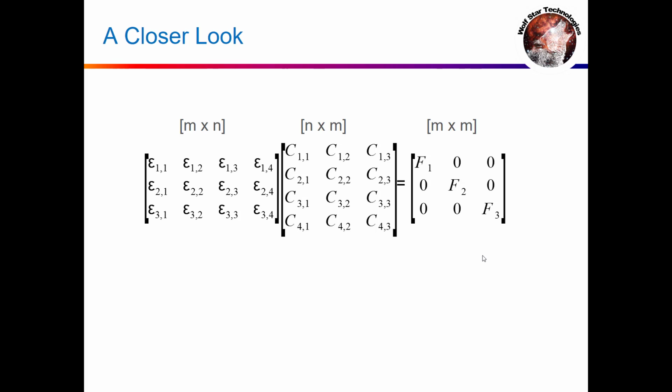So I've talked a lot about loads here, but let me talk about that a little bit more. The loads could be anything. They can be point loads, they can be moments, they can be pressure loads, they could be thermal loads, they could be unit displacements. They could actually even be mode shapes. So we could go in and calculate the mode shapes on a structure and have TrueLoad place the strain gauges on the structure based on mode shapes.